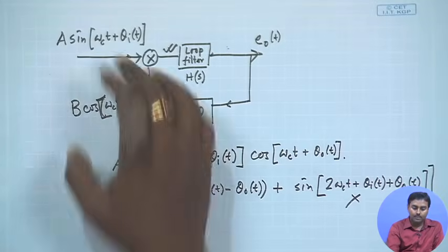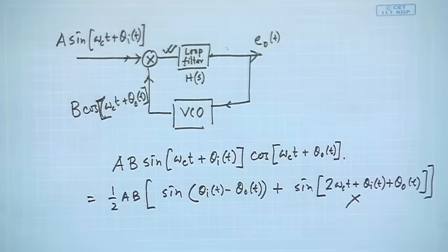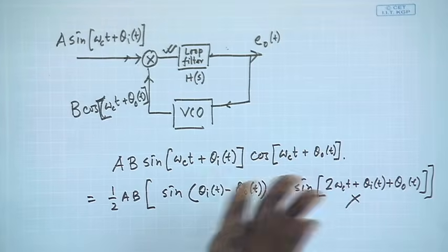So far I have done this. Now let us try to see if I can get an equivalent circuit of this one. Earlier, what I was having was a cosinusoidal. This was the actual circuit of the VCO, where I was putting two cosinusoidals and a multiplier. The circuit immediately becomes a nonlinear circuit, so I have no way to analyze it through linear circuit theory methods. So from there I wish to now transform this to a linear circuit.